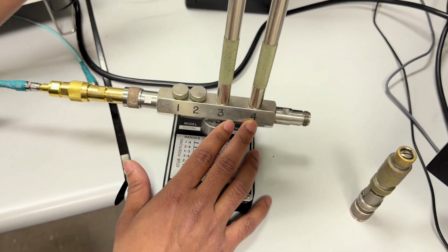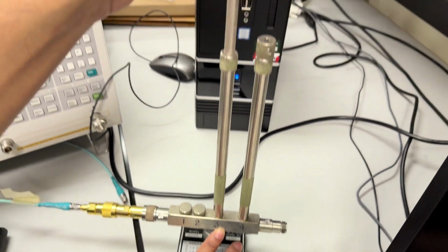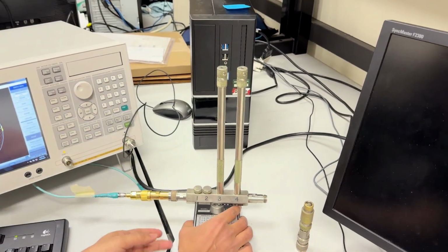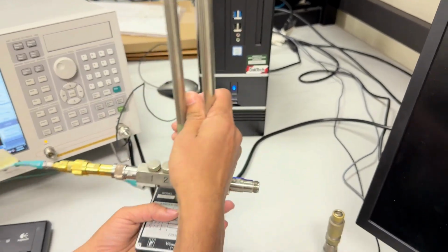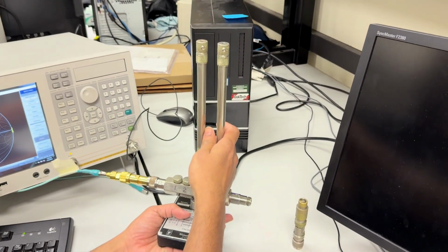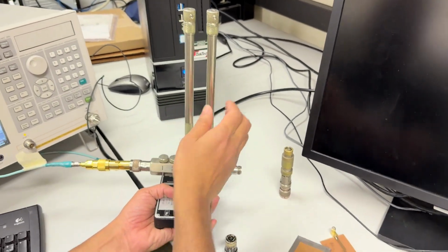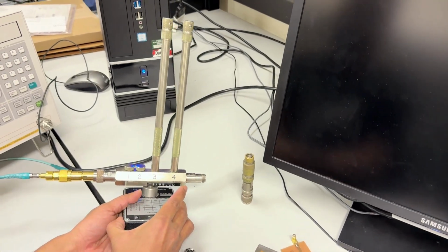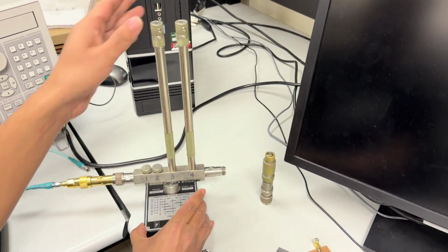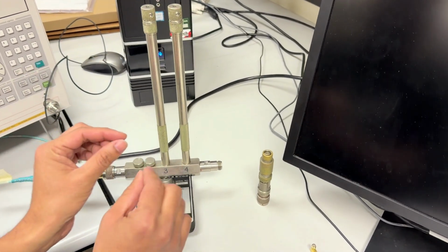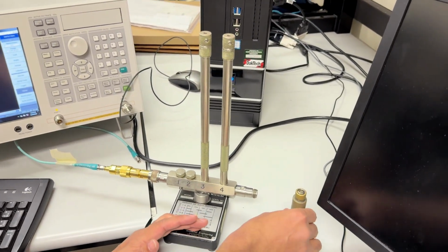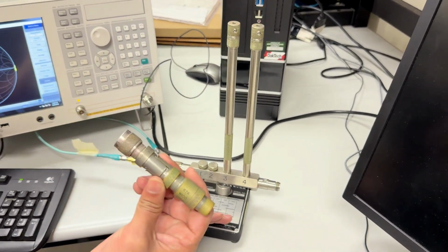We are not going to do anything with that. We'll be changing the length of pole number 3 and pole number 4. So this looks like this actually. This is a very old device, but very nice for visual demonstration of any stub tuner. As you know, whenever we are talking of the stub tuner, we talk about the length. You have to adjust the length to make it more matched with the 50 ohm. And this is our 100 ohm load in this case.